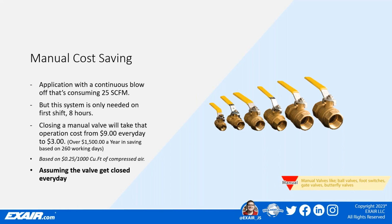So they added a manual valve to the compressed air supply line and added shutting it off at the end of the day to the operator's daily procedure list. Assuming the valve did get closed every day, they went from spending $9 a day to $3 a day in compressed air generation cost. So a $20 ball valve saved them just over $1,500 a year. And of course, this is assuming that valve does get closed every day. As we know, stuff on daily procedures don't always get done. So there is some variable there that you can't control.